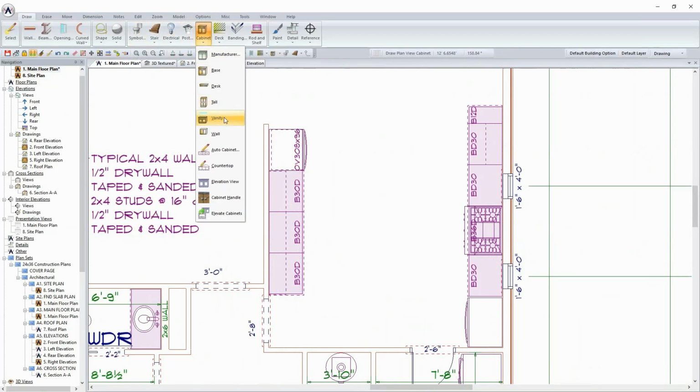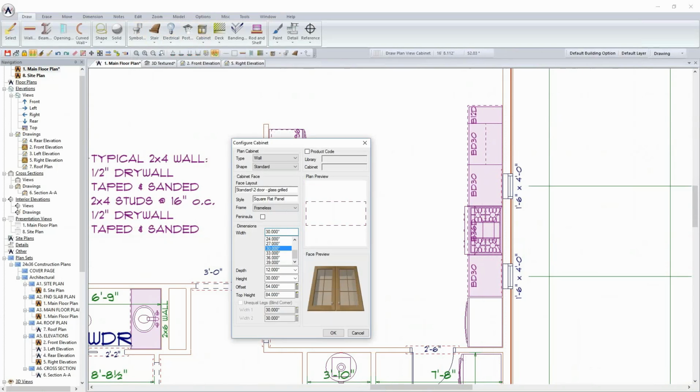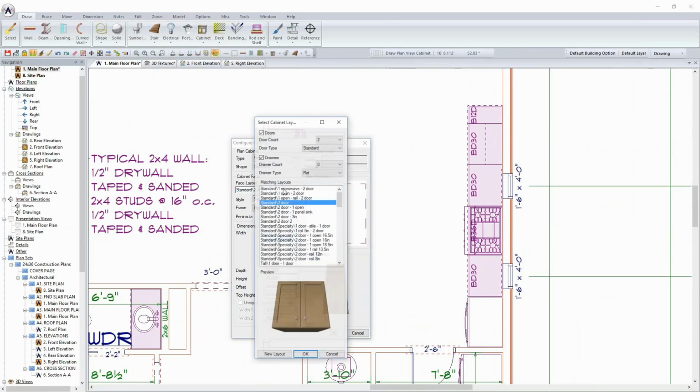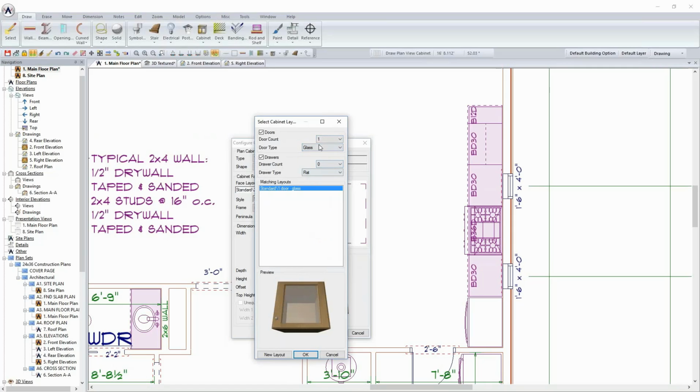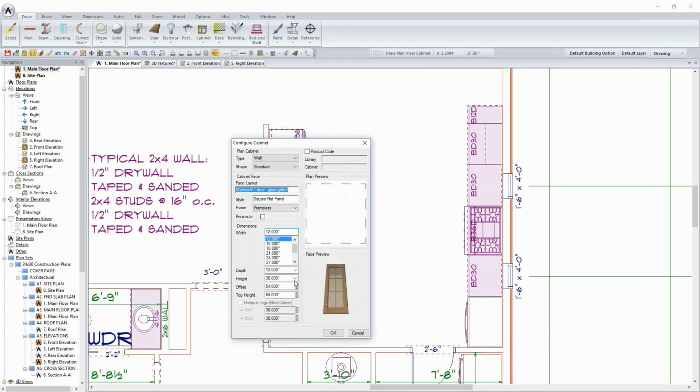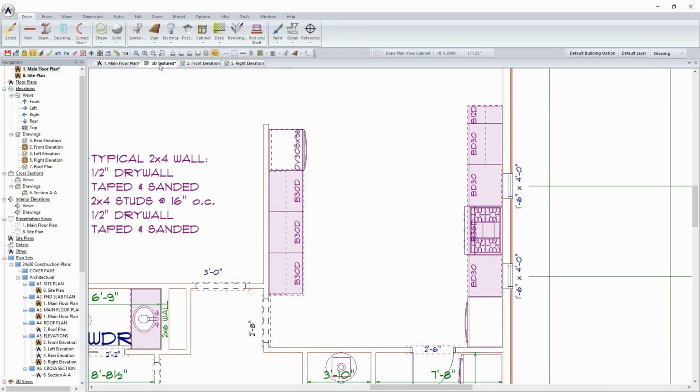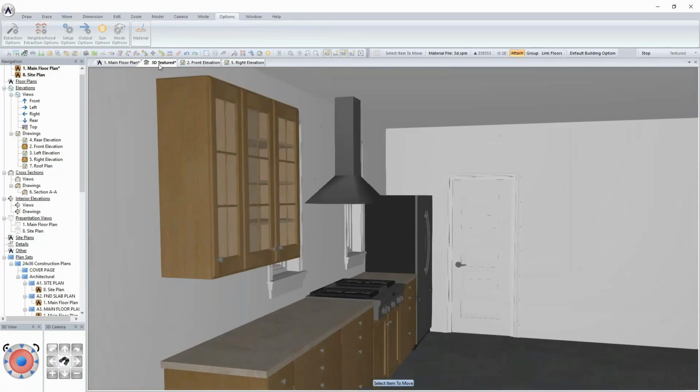And I may also come in through the wall cabinet, and because I've just got a 12-inch and I've not really drawn a 12-inch upper cabinet at this stage, we're going to go to a single door, okay, and in fact I might even go to just a glass grill at this point. Click OK, and I'll change the height, which is going to be 42 inches so that it matches, and now I can click to insert so that I've got just some upper cabinets sitting here.